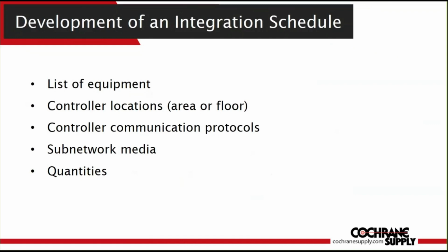So if I've got 250 VAV boxes, right? Well, I want to show those sub networks that are networking those VAV boxes together, whether they're daisy chained or however we connect those VAV boxes, whether it's 35 max or 50 max. We want to show those subnets as a systems integrator because that's the amount of information that's going to be required for A, my as-built, and B, to let me know exactly how much bandwidth is going to be needed and exactly how am I going to actually size each and every one of these switches, right?